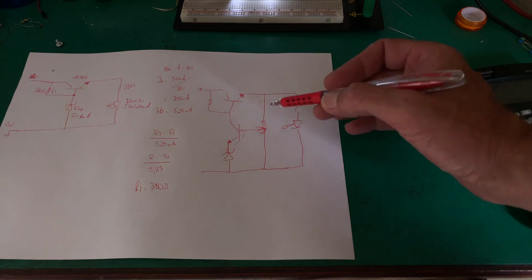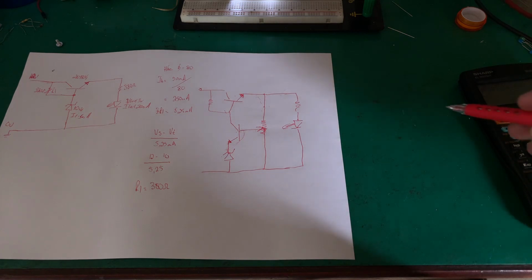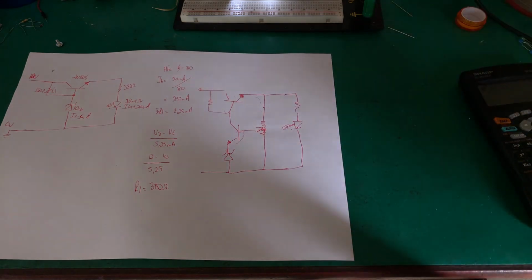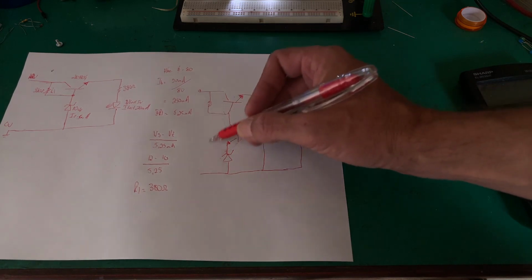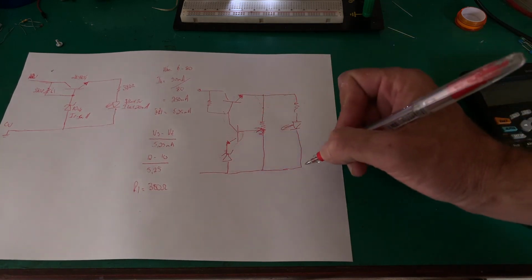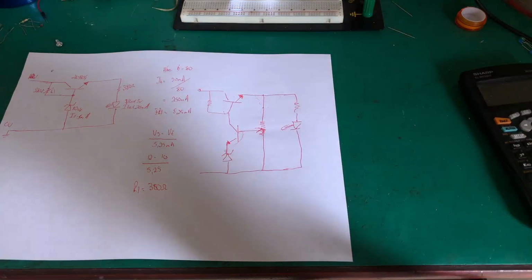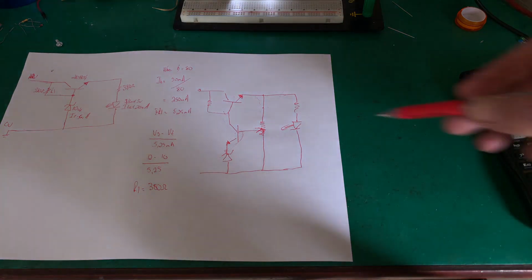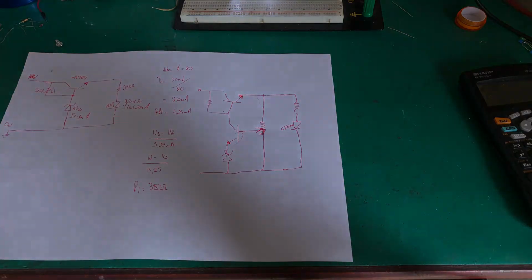In modern day solid state packages like your LM7805 and those sort of things, this is a discrete package, and this feedback is actually achieved through a differential amplifier. So you could actually replace this. You would have your Zener as your reference on one side, and you would have your feedback as the part to add into the circuit. So very simple. Let's get on the breadboard and let's have a look.